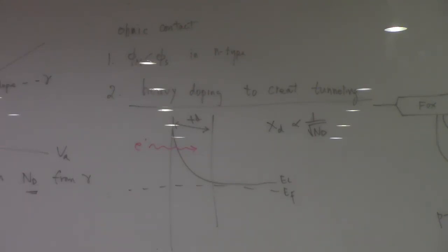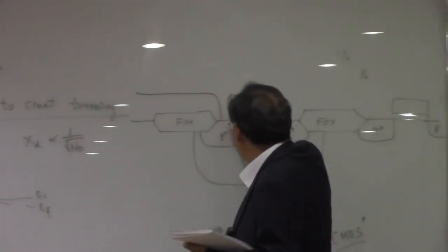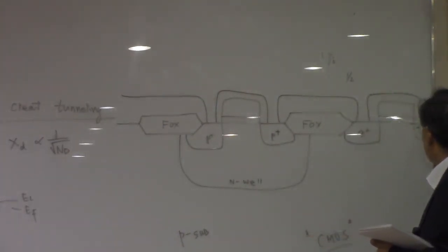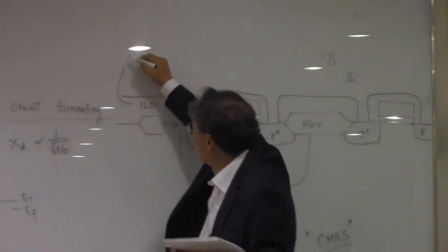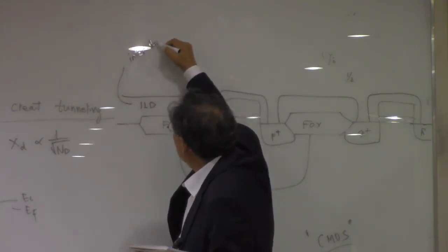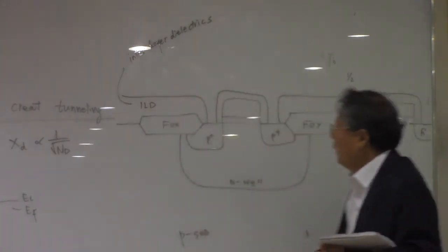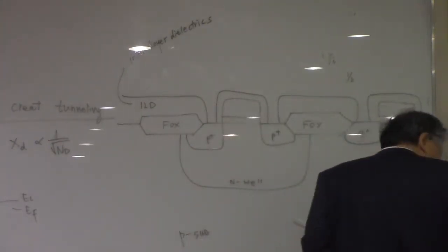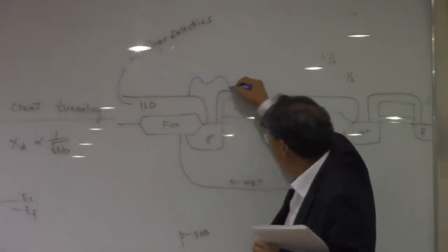It's for memory devices. Now, when you finish this foundation, you're going to deposit the dielectric layers like SiO2, things like that, and make a contact. We call that contact. And we call this interlayer dielectrics. Okay, and then make a contact hole, and then you should deposit the metals and make a pattern so that you form metals like this.